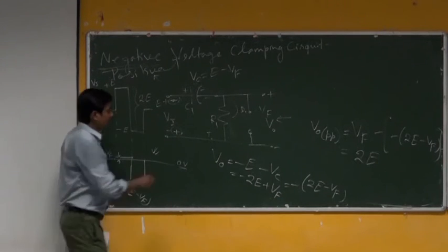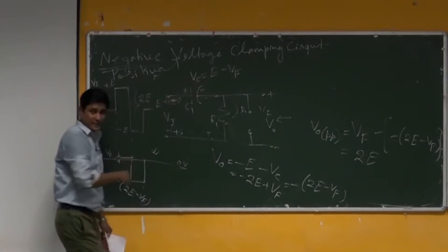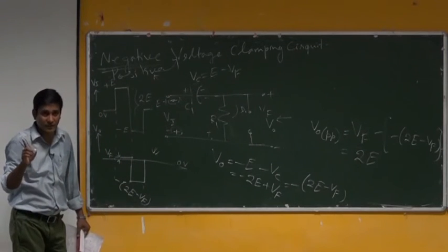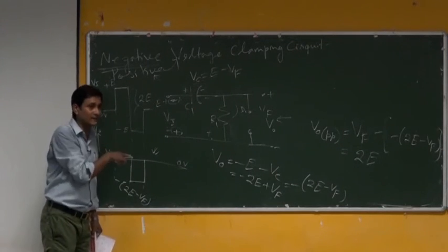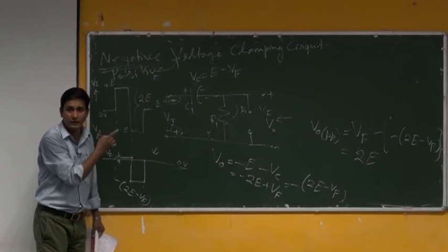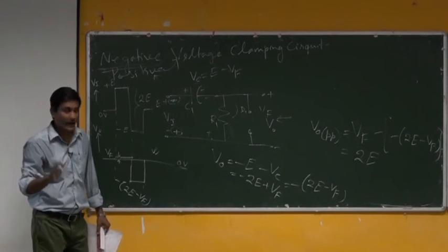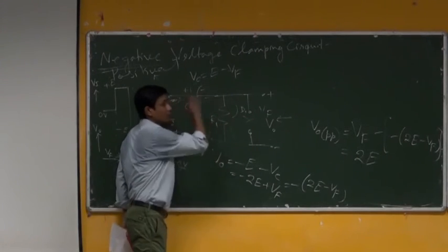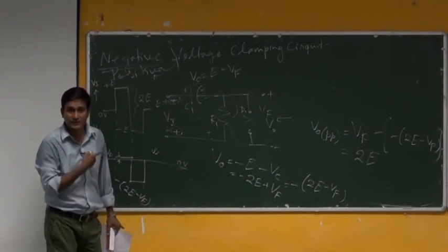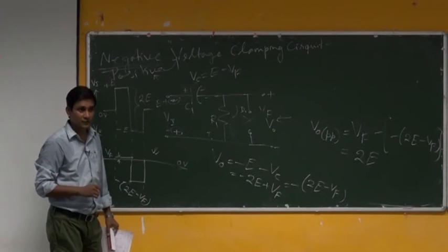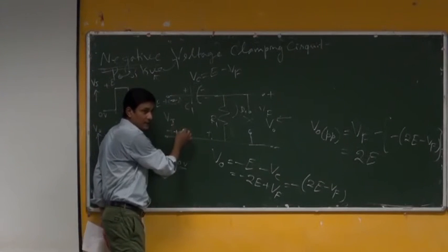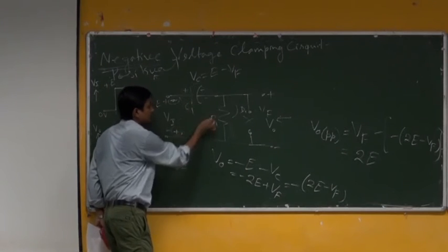Now, think about any current flow in the circuitry, because the diode is not in the picture. If the diode would be there, you would be influencing others. But the diode is not at all there, since it is reverse biased and has gone open circuited, so the remaining circuitry exists with this R1. Some potential is applied across this circuitry where the loop is complete.